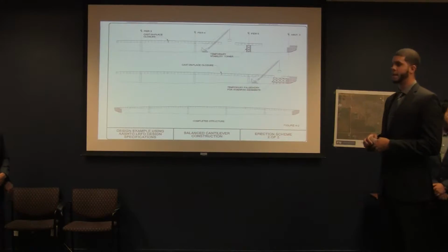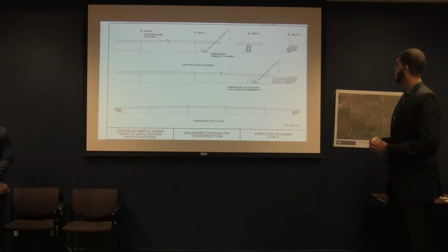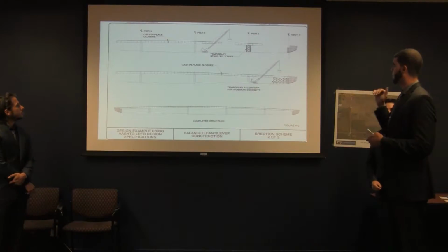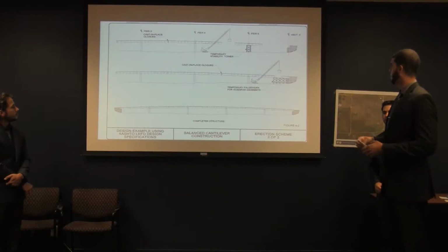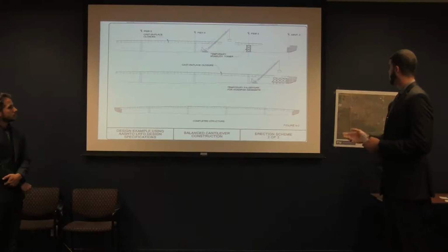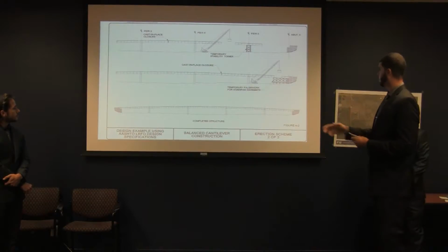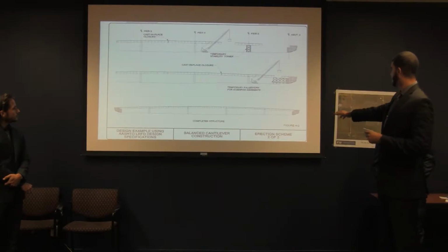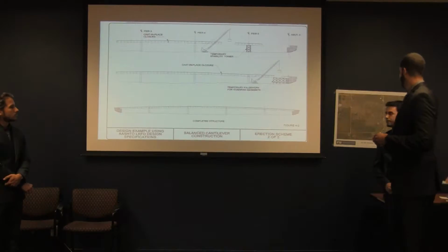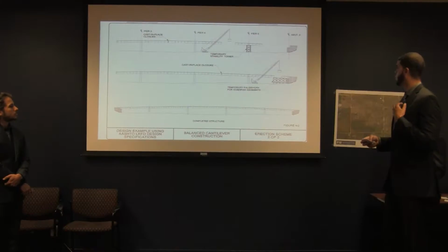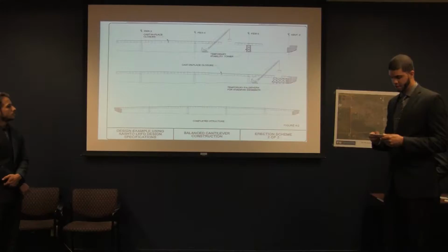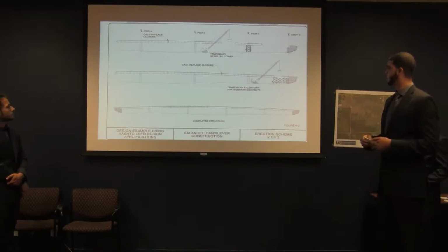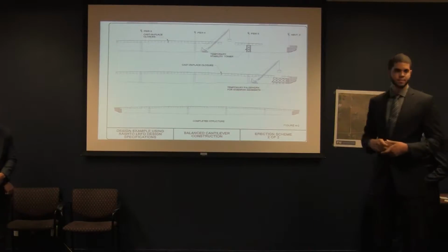On the top we have a crane, but we really would be using a gantry, which places each segment and uses the existing roadway as a place to build the rest. And the bottom is the completed structure, but towards the end, instead of that, it'll be an abutment. And also, there's going to be 200-foot spans between the piers, and 155 piers at a 20-foot elevation.